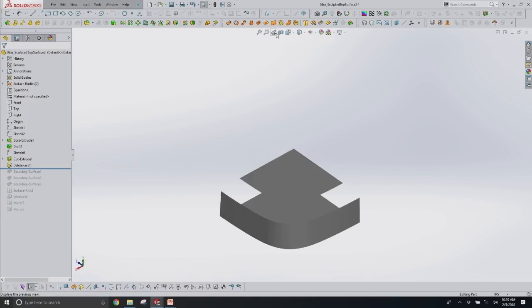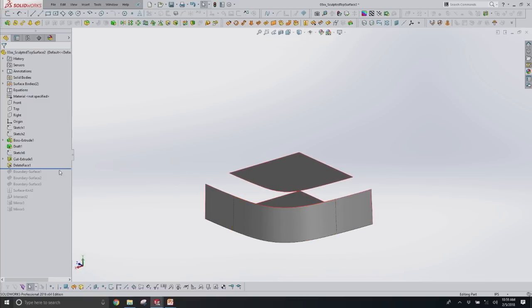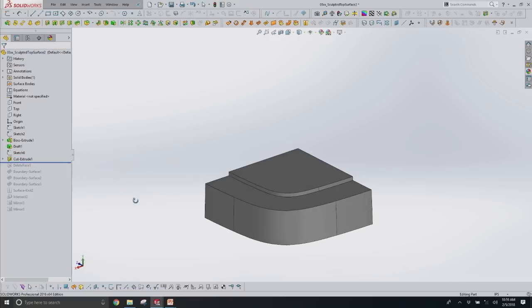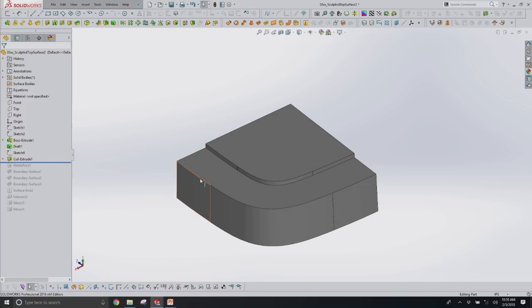So let's turn this back a little bit. So instead of building a scallop, I'm going to build a pillow shape. So the way I'm going to do that is I'm starting with a cut. Before I start surface modeling, I'm just cutting material away. So I'm creating a cut, and this generates two new sets of edges. I didn't have this edge before, I didn't have this edge before, but now with the cut, I do.